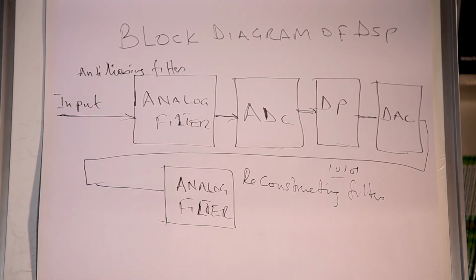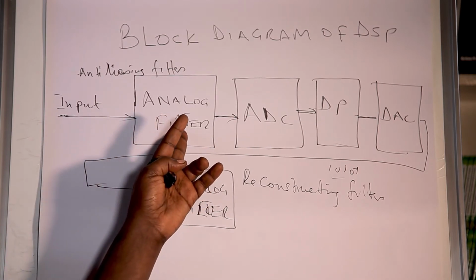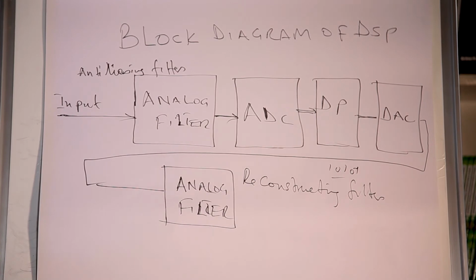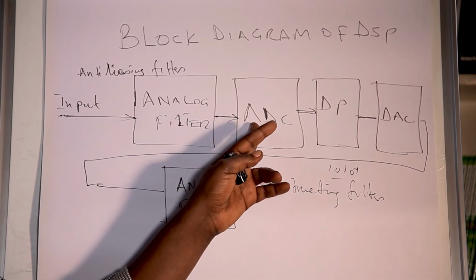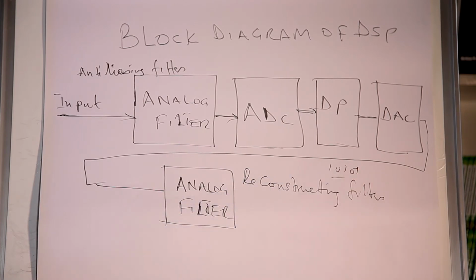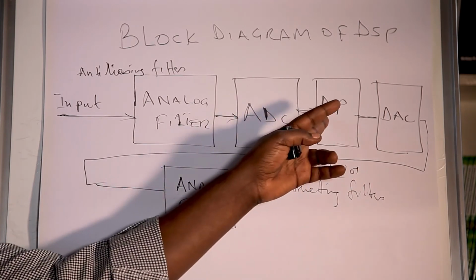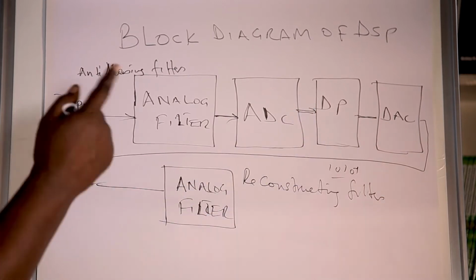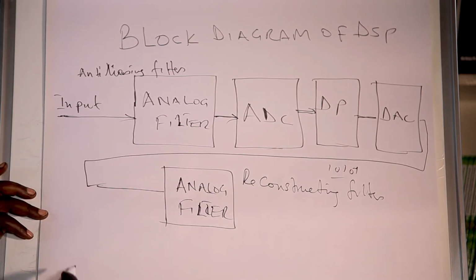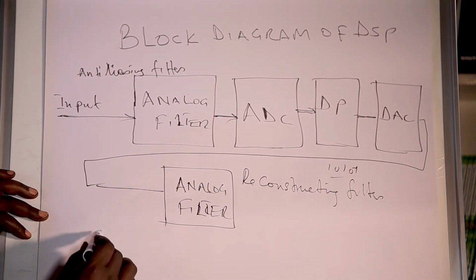Remember, in most cases the signal comes in analog format. It has to pass through the analog filters, then go into the conversion to get the corresponding digital equivalent using the DSP, and then you can regenerate it again using reconstruction. So at each stage, for example at the input, the signal will look like this.